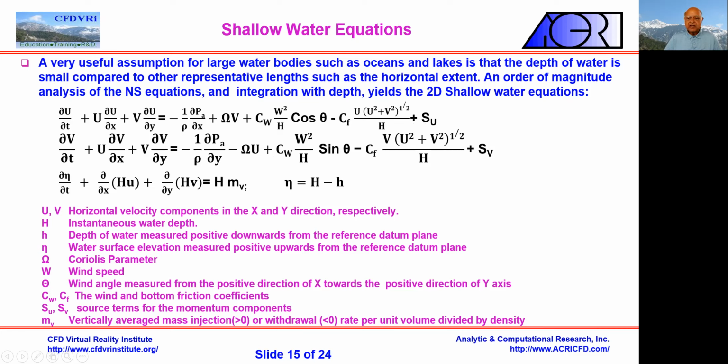Let's assume that there is a calm sea surface called the datum level, or let's say the sea level. Now the total water depth at any point can be decomposed into a time constant factor, which is the depth below the datum. The depth below that level is constant because the ocean bottom, we hope, is not moving. And the amount above is the departure from the total depth. So we denote the departure by eta, total depth by H, and the depth below datum by h.